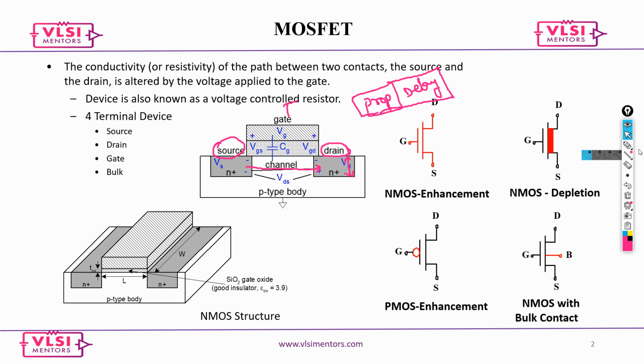So it is basically the amount of time it takes to charge this drain. The moment your gate is turned on, the charges travel and the drain becomes completely equivalent to your VDD. The drain gets completely charged. That time is what we call propagation delay.